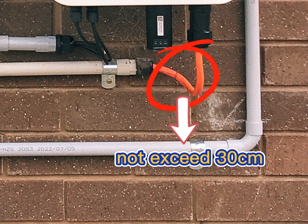1429.1.2006 stipulates that cables must be put into the conduit outdoors and can be exposed in places inaccessible to people indoors. DC cables must be put into conduit fully, and the length of exposed cable next to the inverter should not exceed 30 centimeters. Although the photovoltaic cables in a solar project can withstand UV radiation, extreme temperature, and humidity, and are durable, we still need to put DC cables into the solar conduit for safety and beauty.